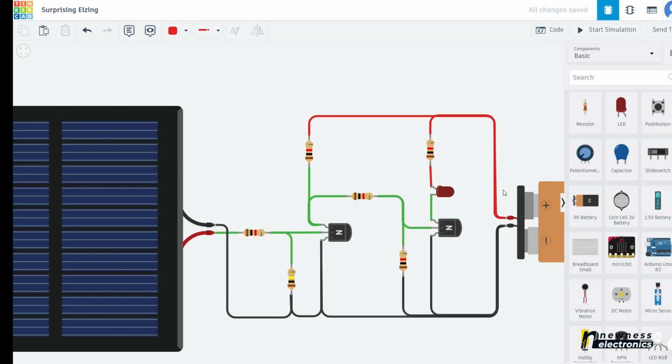Okay, now we've designed a simple security light setup that only turns on when it is dark and turns off when it is bright. Let's test this. So don't forget, once current flows in through the solar panel to the base of this transistor, the collector will be off. And once the collector is off, there's no voltage in the collector. So the output voltage here will be 0 volts, and 0 volts will enter into the base of this one. Thereby, this LED will not turn on.